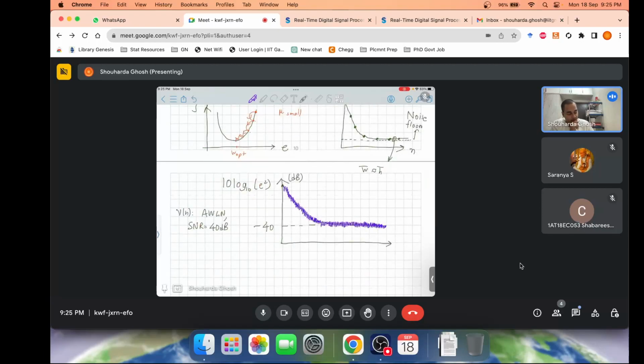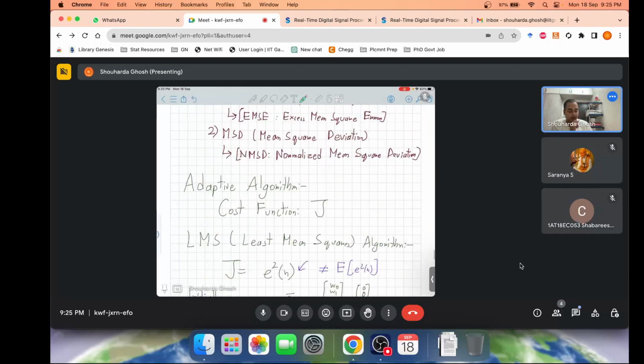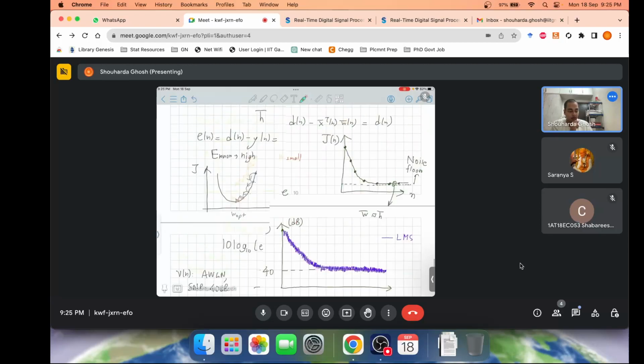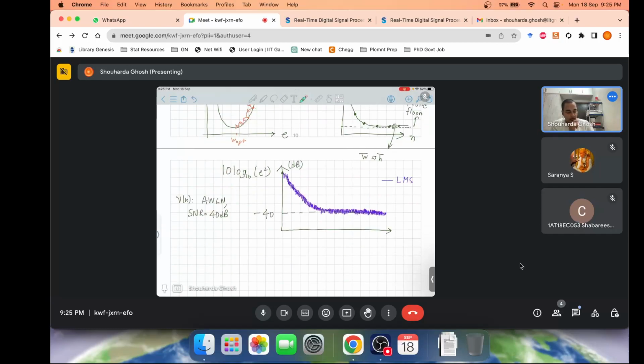So for LMS, this color I give for the LMS, assuming that you have used a step size which is small enough to converge correctly at the right coefficients, and then the convergence is in the mean. Why am I saying the mean? Because if you see, the error is oscillating around the noise floor, it is not becoming stable, it is moving around, okay. This is the noise injected due to this approximation of the cost function. Fine. And that's when you use an optimal mu.